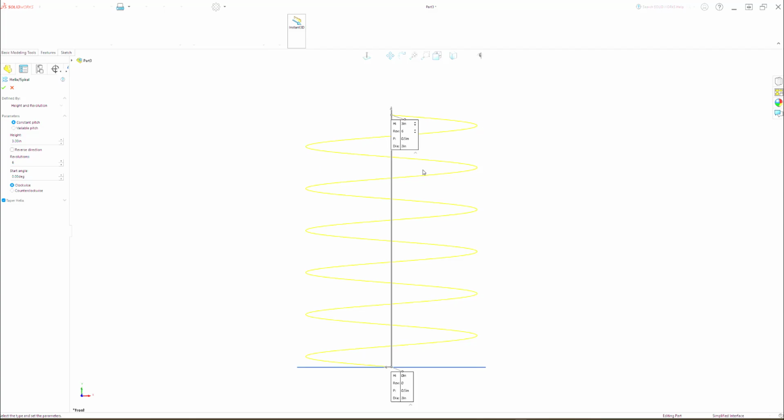And again, if you're using a compression spring, this is the distance that the object could compress minus the diameter of the actual spring material that you design for 3D printing. So you've got to take that into account in terms of the pitch distance. That's why I like working with the pitch, because the pitch is a key element of what you're working with. So the diameter of the spring itself is important because that gets subtracted from the overall pitch distance, and that gives you the distance that the compression will take place.